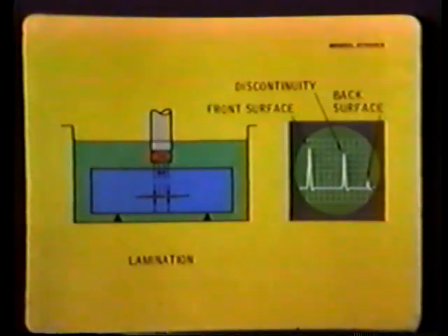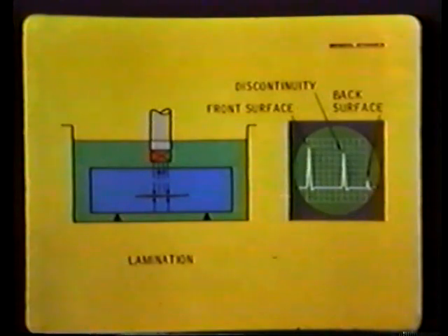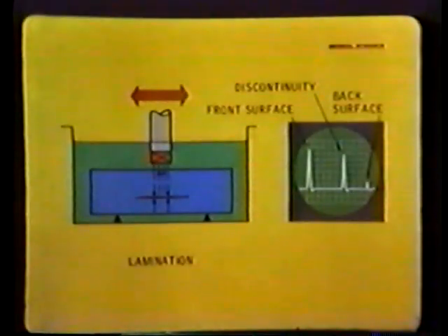Discontinuities larger than the diameter of the transducer usually produce an indication that saturates the screen. A partial or total loss of back reflection is typical, since the discontinuity reflects nearly all the sound energy. The extent of the discontinuity can be evaluated by noting the distance the transducer can be moved and still receive the indication.